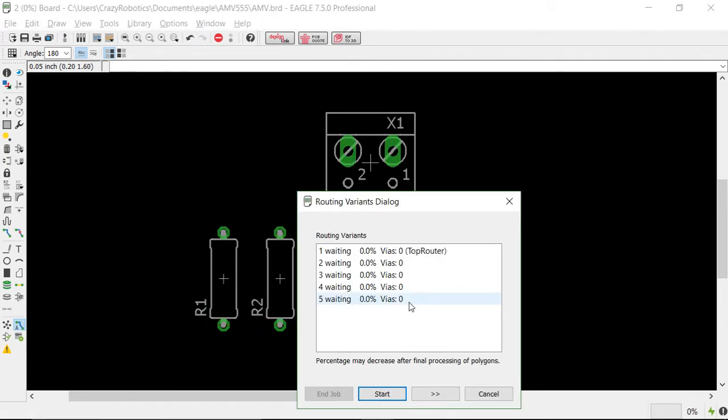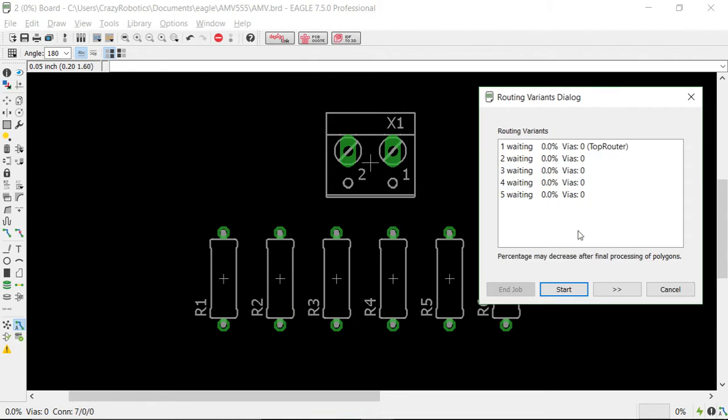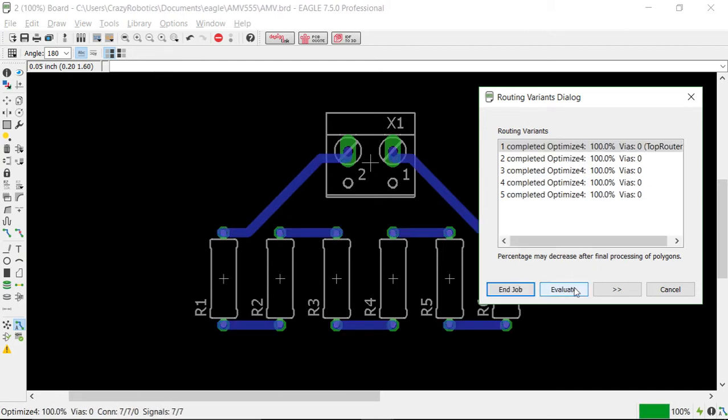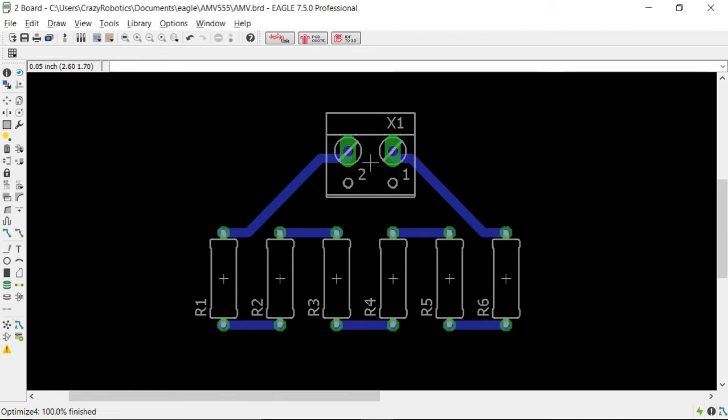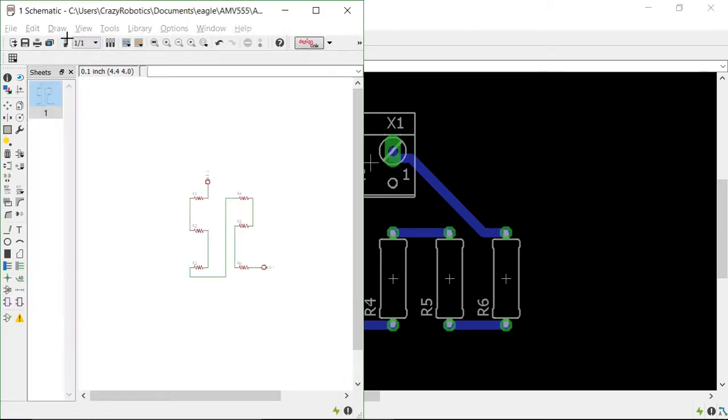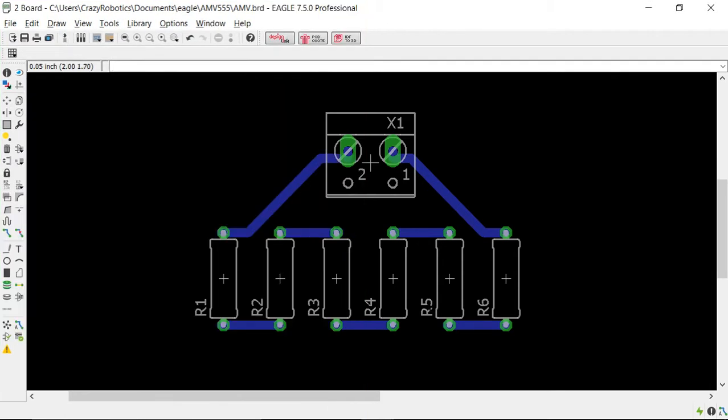Click on continue, click start, and in the meanwhile keep an eye on this particular section. Now you'll observe that whatever connections we have considered in our schematic file have been adopted directly into the board file, which were displayed with some yellow connections between the pads.